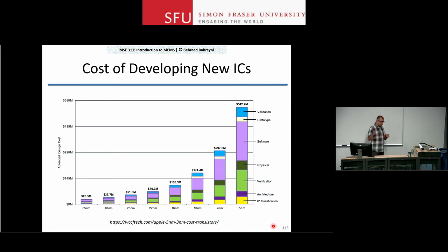So what I can do, for example, if I have a 10-core processor on that chip, and I take this out after the fabrication, and I notice that one of the cores is not working, right? Something has happened. I have to have that kind of prediction in my design that if one of these cores is not working, I just take it offline.